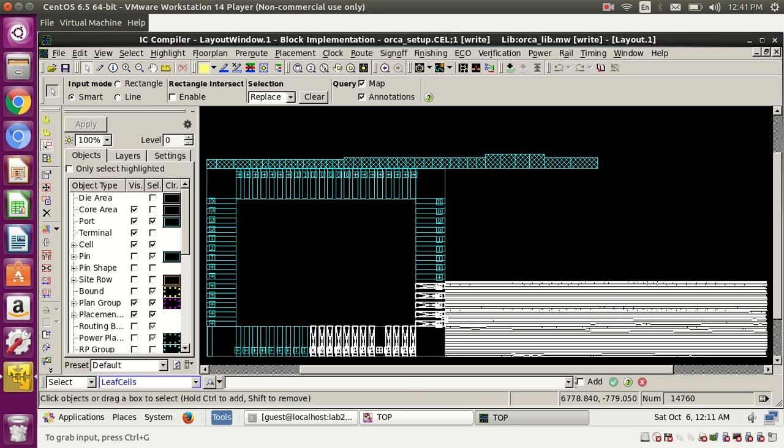So whenever it is parallel, our concern is that because this is clock and this is data, the data may rise and come fast or slow. I think you have seen this. Because it is rising, it may come up and then go down, so that means the delay will be decreased. And if it is coming down, it will come even faster. So we have two conditions.